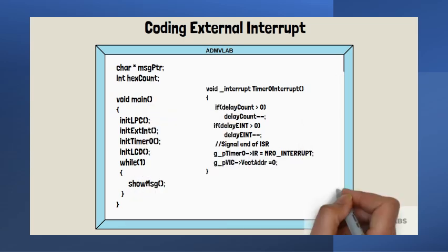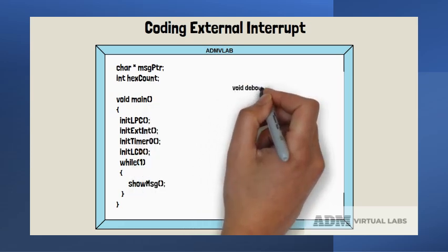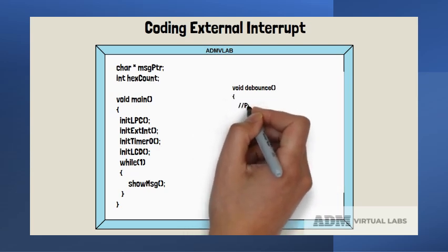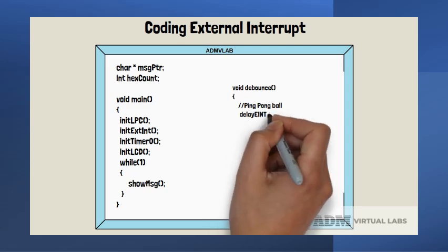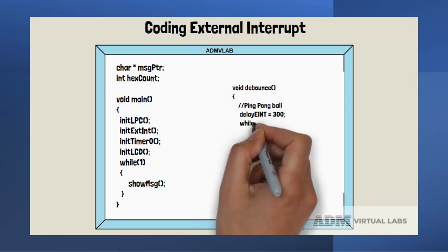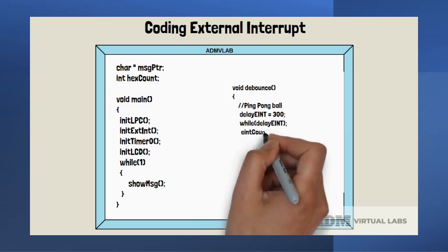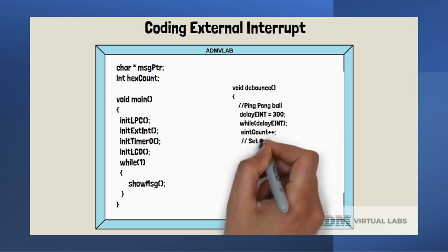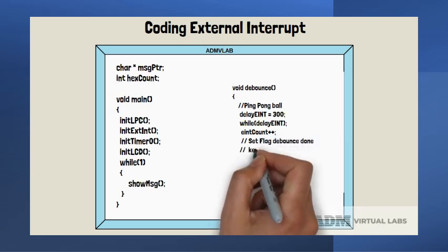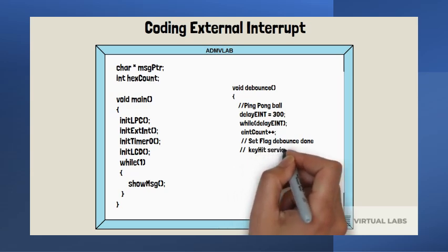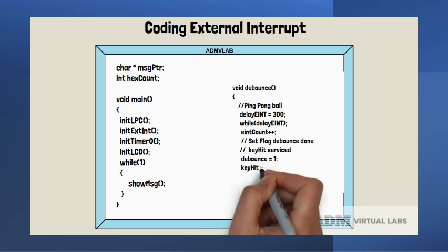We normally take for granted that a mechanical switch is an ideal on and off device. But in reality, the switch behavior is like the dropping of a ping pong ball. The switch state oscillates between on and off multiple times before settling in its new state. Normally a switch ceases bouncing in less than 5 milliseconds, but a switch state counter will increment multiple times. Hence, debouncing switches using software is the only way to go. We use a timer, wait for a delay time, a constant for external interrupt, and then go ahead to increment the external switch count.